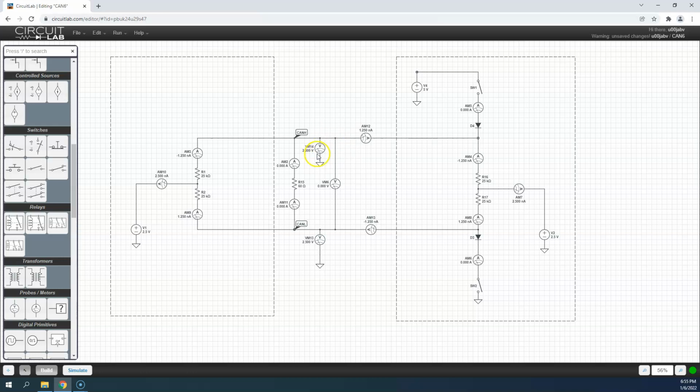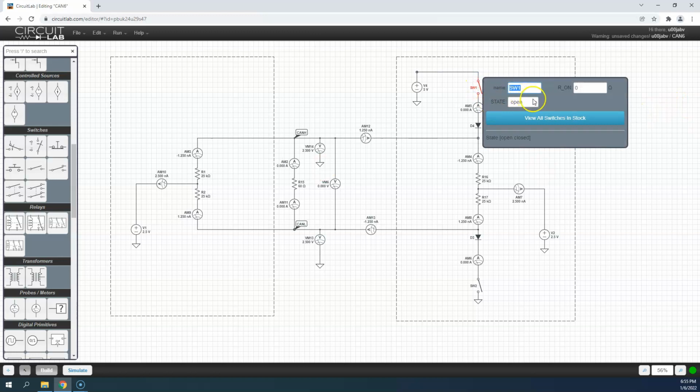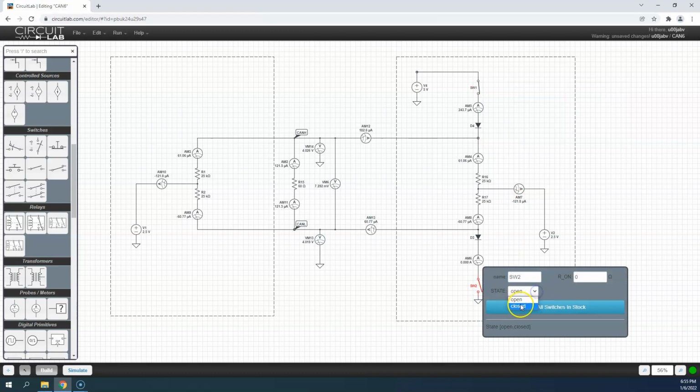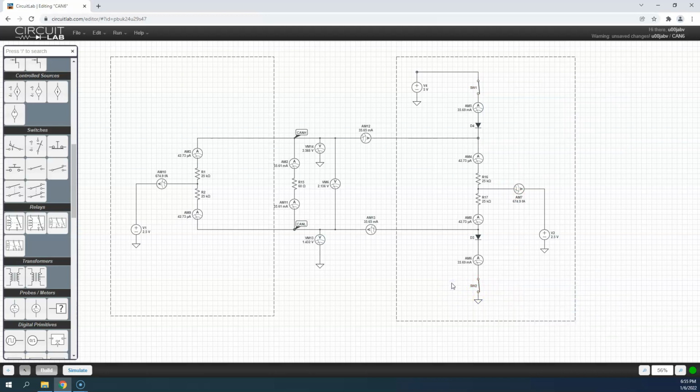But anyways, this is the concept I wanted to get across: I have to drive it to get it to the dominant state. So I have to have both of these switches closed. Please don't look at it with one closed. That's bad. When I have both switches closed, we can see that I've driven the data link to high. This guy can still be 2.5 volts, and the reason is that there's no current flowing here.